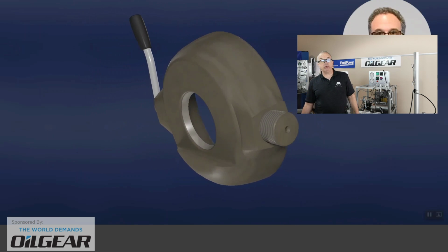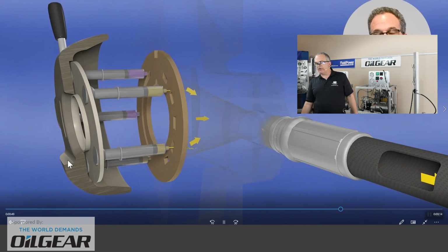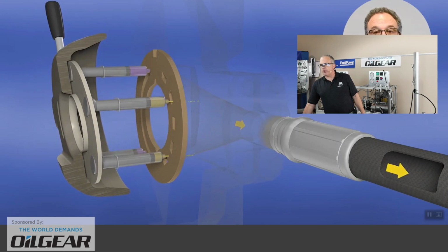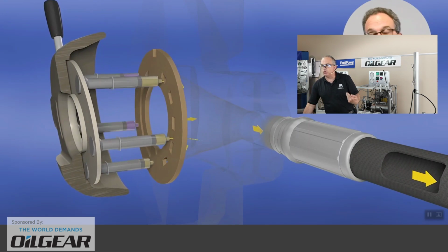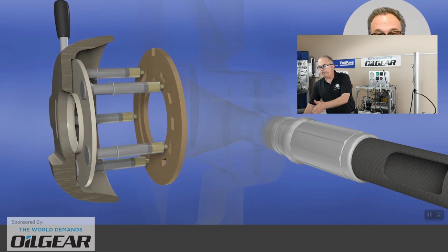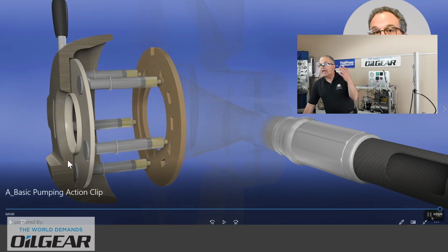Here's a simple one where we've left the handle in play. Not very common to have a handle. Oh yeah, okay, so what we've done there is change the angle to half. So now our pumping rate is slower because our pistons only draw back so far and only discharge. Oh, hey, what happened there? I think our swash plate went to the perfectly vertical position, and now our pistons no longer draw in fluid, nor do they eject fluid.